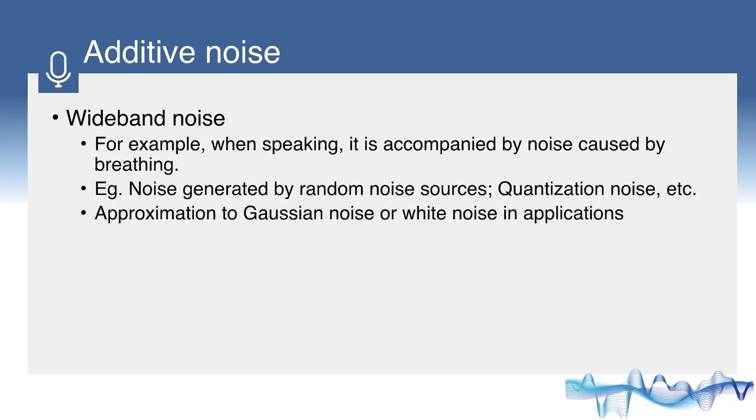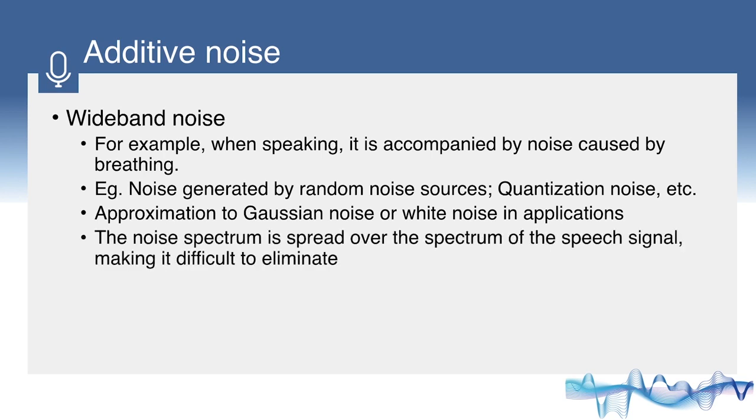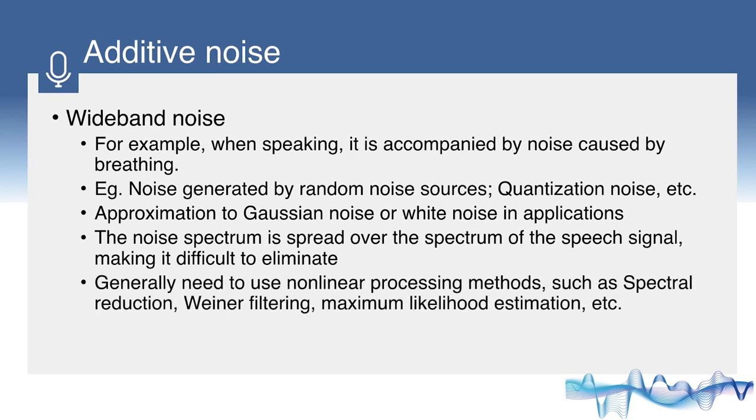In applications, wideband noise is approximated to Gaussian noise or white noise. The noise spectrum is spread over the spectrum of the speech signal, making it difficult to eliminate. Generally, we need to use nonlinear processing methods, such as spectral subtraction, Wiener filtering, maximum likelihood estimation, and so on.